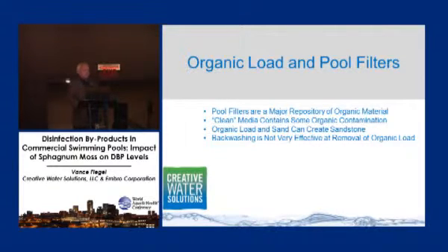Organic load and pool filters. Pool filters are a major repository of organic material. That's part of their job, to catch everything that comes through. So they catch all the organic material that they can filter, such as cells and hair and things of that nature. But because of what we know now about biofilm, there's a lot of actual growth of organic matter upon the sand in a sand filter.